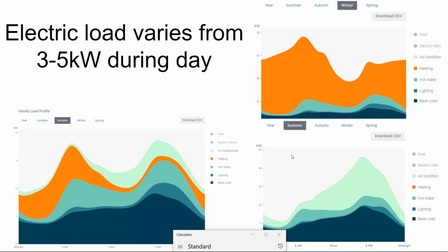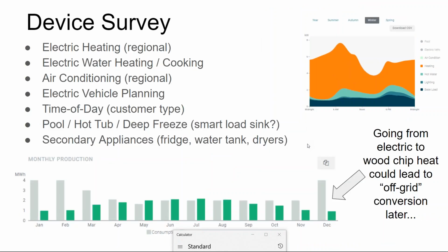I really only think this stuff is useful as a sanity check to make sure that your inverter is going to be able to output enough power. And so what I would do instead is log into my electrical account with my power company and see if they're providing the 15-minute interval data available as a download.